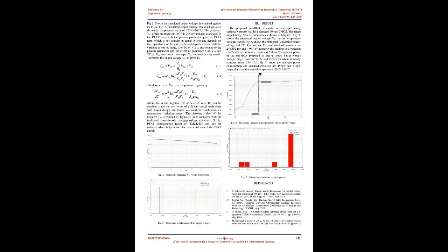The transistors PM2 and PM3 are current mirrors, and the size of PM3 is approximately 2 times that of PM2, similarly PM4 and PM5. The transistor NM11 is a diode connected NMOS, so the current through NM11 is the same as that of R2. The PTAT voltage generator consists of transistors NM4 to NM7, all of which work in the sub-threshold region.